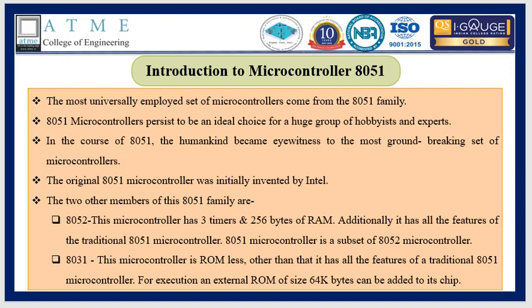The two members of the 8051 family are 8052 and 8031. The 8052 microcontroller has 3 timers, and it has 256 bytes of RAM. Additionally, it has all the features of a traditional 8051 microcontroller. We'll discuss the features of this 8051 microcontroller in our upcoming slides.